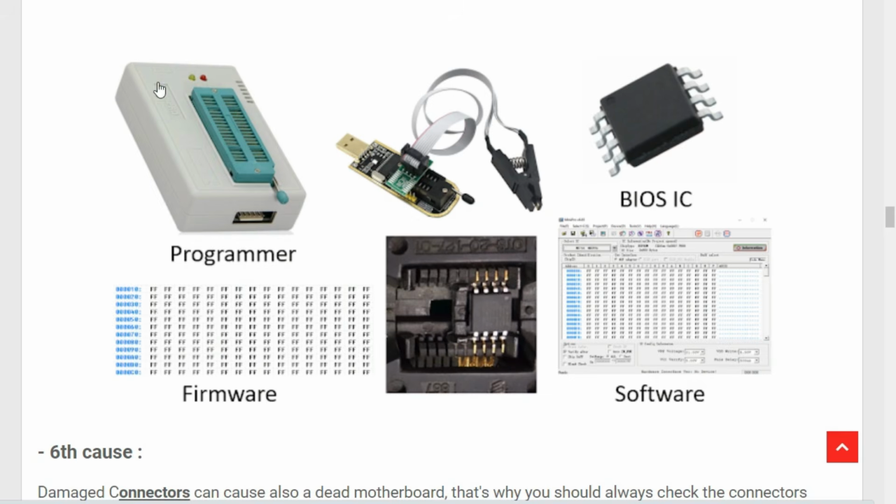Okay, so we have the programmer here. Using this programmer, you should remove the BIOS from the motherboard, connect it here in this support, and then connect this support to this programmer. And then reprogram it using, of course, the computer. You can find all these programmers on Amazon, for example.